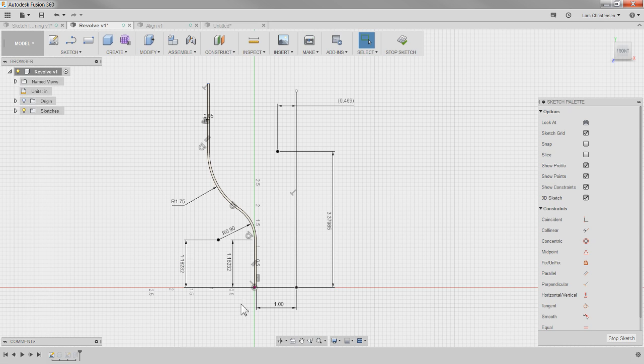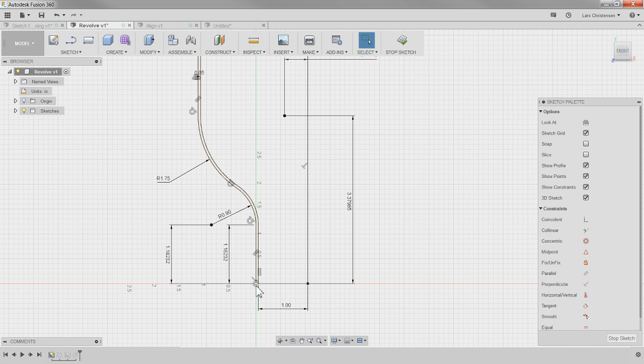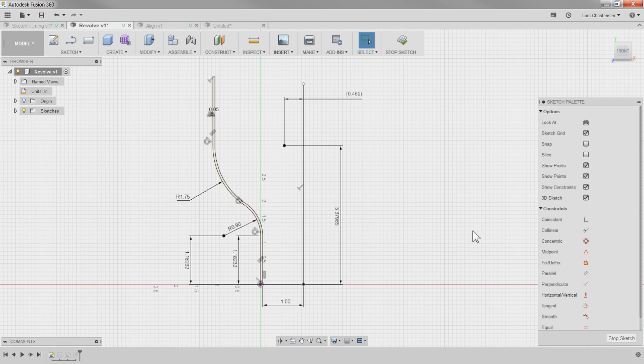And this is just really, I sketched up this line with some tangent arcs. Then I used the offset command to give it some thickness. I connected the 2 ends. And I actually drew it up right on the origin here. So I just created a line 1 inch over that I'm then revolving around.